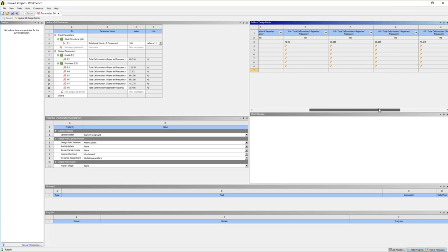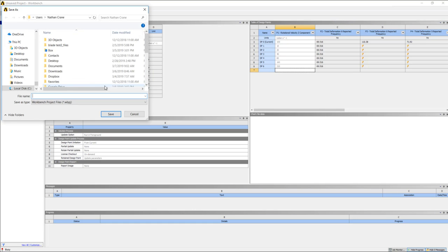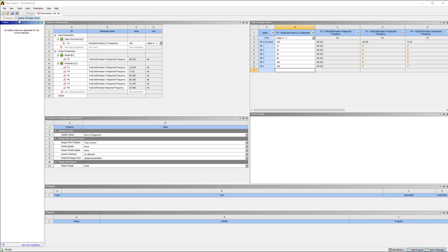And I have here all my frequencies, so I'm going to go ahead and save my project, and then I can run. I'll just update all design points, and we'll give that a minute to solve, and then take a look at the results.